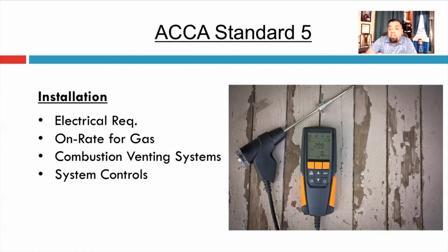Your combustion venting systems need to meet local code, right? Obviously, OEM instructions are important, but the National Fuel Gas Code, NFPA, IFGC, all of the venting needs to meet those requirements. I mean, that's basic code. If you're pulling a building permit, it needs to meet that code anyway, or a fire permit for oil, right?